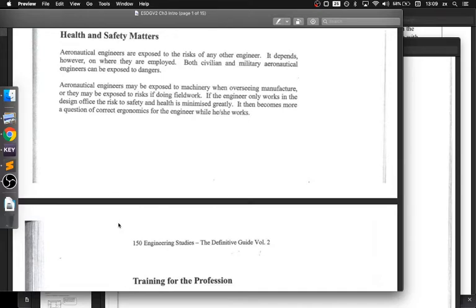Something we will talk about later is factor of safety, and the fact is that the factor of safety on planes is much, much lower than the factor of safety for cars or for structures, and that's because we need our planes to be very, very light in order to improve fuel efficiency. How we compensate for that lower factor of safety is with much higher maintenance, and that's how we manage to get those advantages.